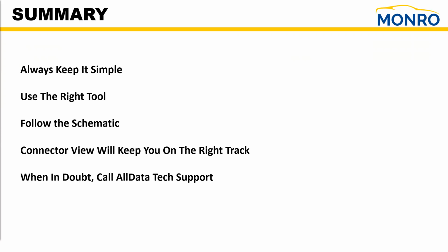Use common sense. I'm looking for open circuits, usually when an external force has acted on the vehicle. Follow a schematic. The connector view will keep you on the right track. And remember this, don't be afraid to get involved. When in doubt, pick up the phone, call All Data Technical Support. They're there to help you on the back end.